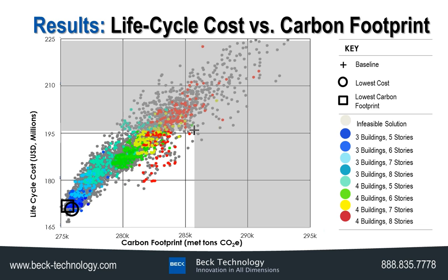And you would think, conventionally, that having the building with the smallest footplate, i.e. it's the tallest building and the most number of those buildings, would be the most expensive option by far because you've got the most cladding. Right? So your floor to cladding area ratio is horrible. But this shows us there are a number of really good models inside of this design space that are better than our baseline.